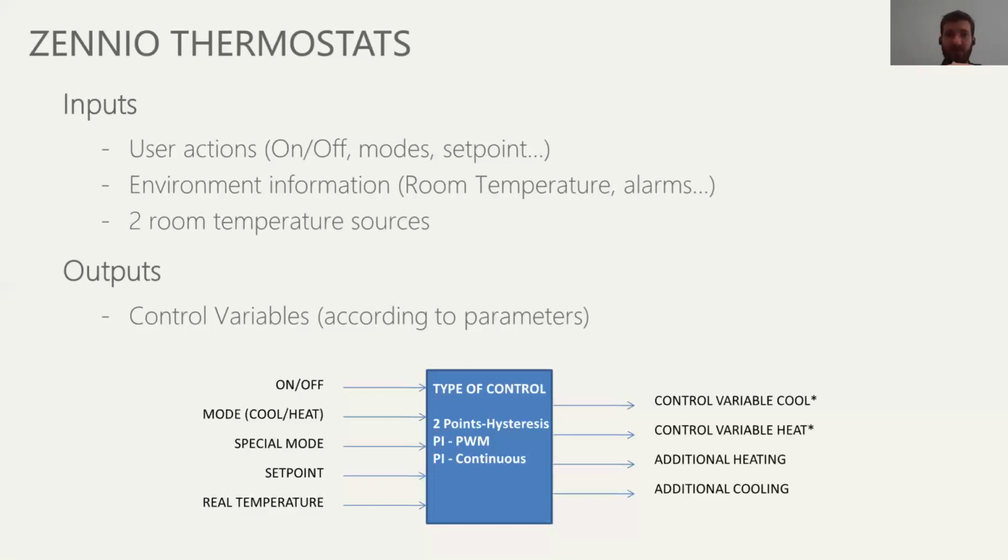Very useful if you think in low values where you probably haven't seen the valve open because when you checked, it was already closed. And then you go to the user interface and see, oh, it's 10%. So it's just been open for a minute and a half, something like that. So very useful in all those scenarios to have the 1 bit object and the 1 byte object to use as information.